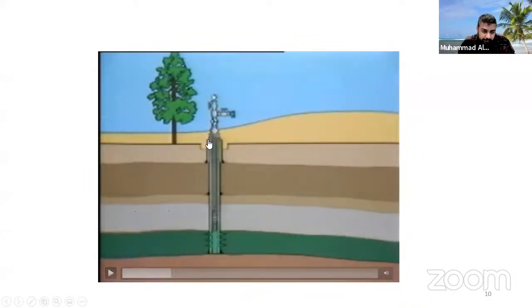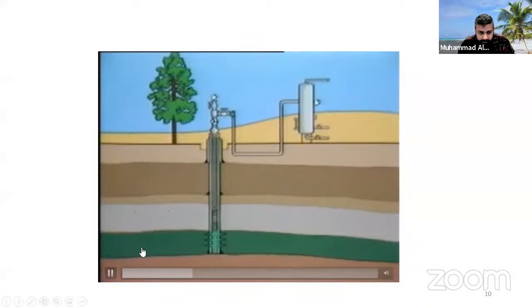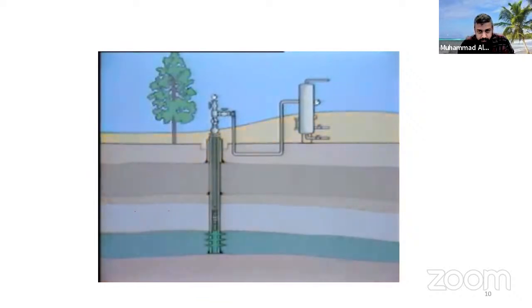During the drilling process, we will install our casings like this one. This one casing, there's another casing. Then we install the perforation tubing. Then we perforate them. It means we create holes here. We install our Christmas tree, choke, surface flow line, and separator. We have our flow lines. Then we have our separator here. These elements are sufficient to illustrate the concepts involved in describing the pressure flow rate relationships of our production system.